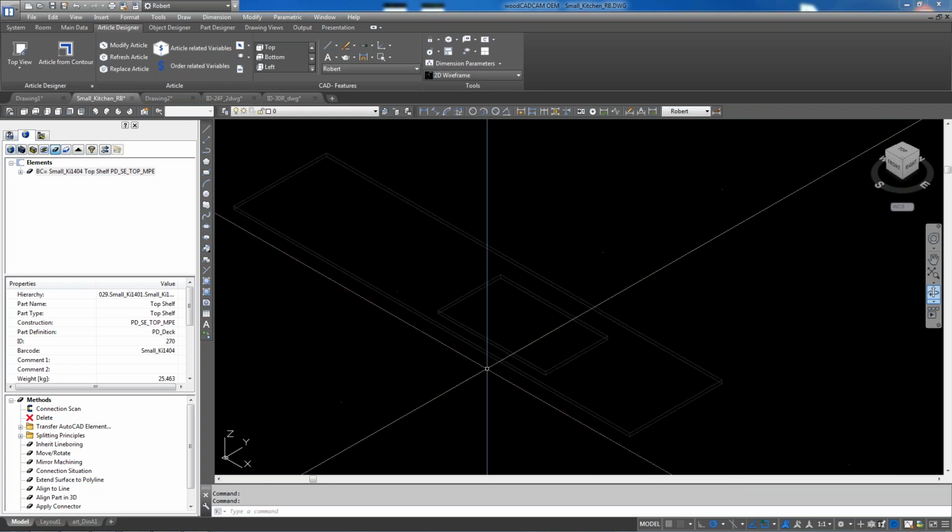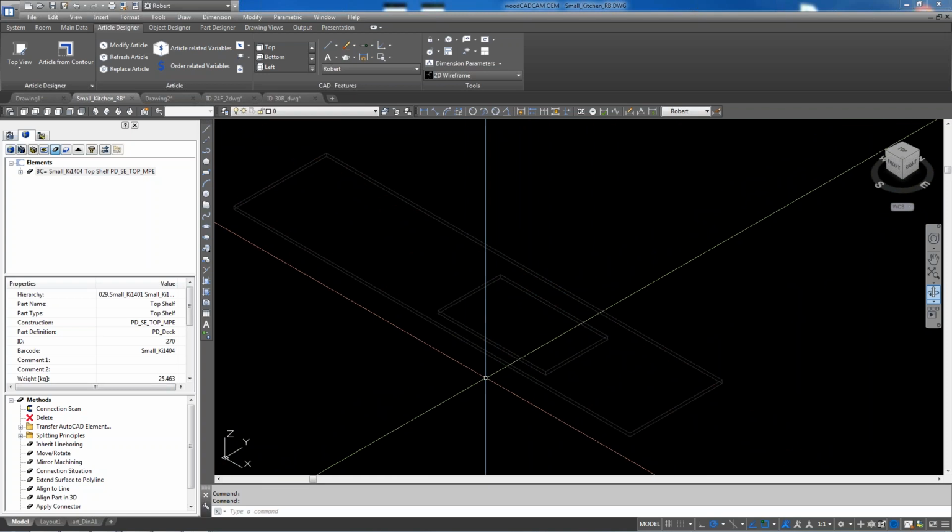All right, whatever I've done, I messed up something. Just remember though that if you really want to run this on the CNC and cut that, you want to actually draw the polyline with the radius corners that you want for the actual cutout. Right. Okay.